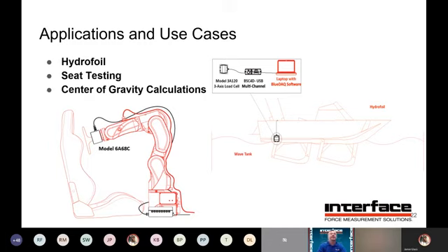Center of gravity, lots of systems, you say multiple load cells. Say if you want to measure the center of gravity of a plane. You would have a system where you might have, say, 3 or 4 load cells beneath the surface, and then you could measure the CG within that. With a single multi-axis sensor approach, you can also do something similar, but it can be done with more complicated geometry and done in multiple axes.